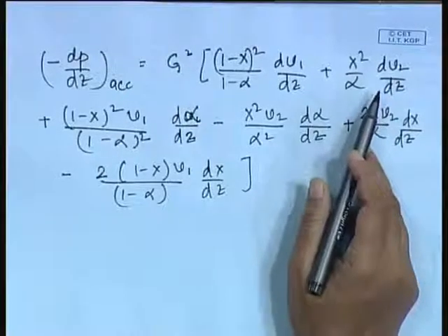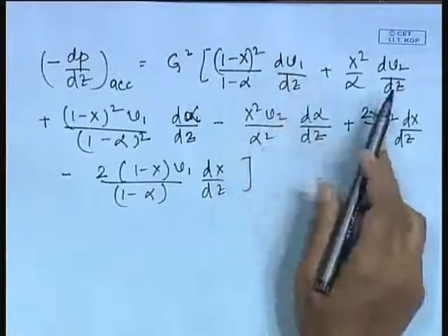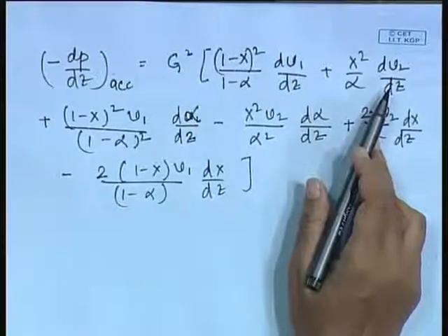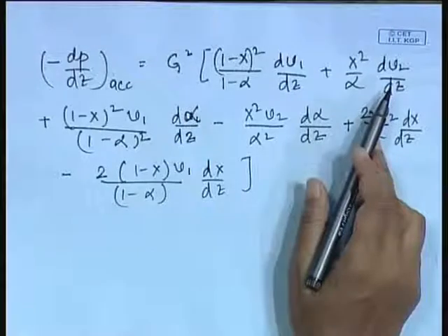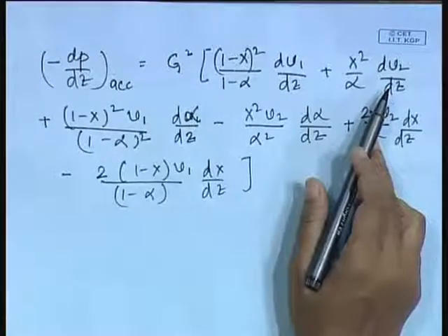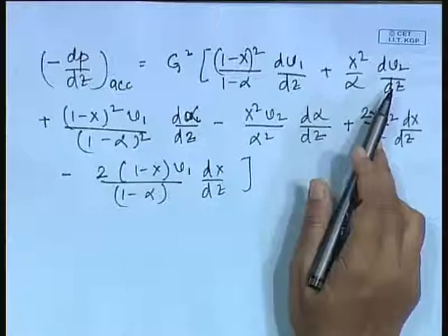Now, here we find that why does v1 or v2 vary with z? Any idea why v1, v2 vary with z? Just because pressure varies with z. They are a function of pressure. How to know in what way they vary with pressure? One is the PVT behavior of gases, or simply from the equation of state we can find it out, isn't it? Or suppose there is a change of phase, then we can also find it from thermodynamic tables as well. Okay.